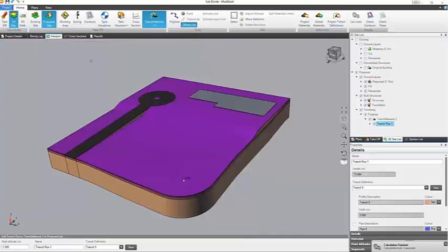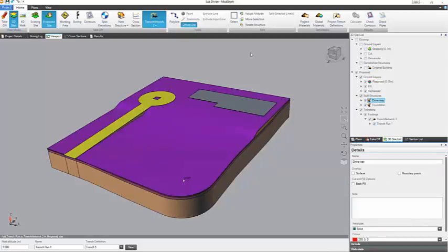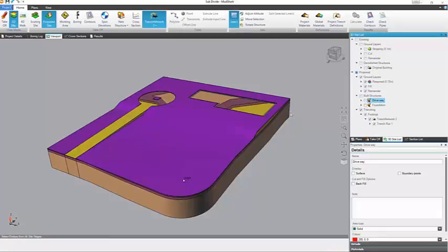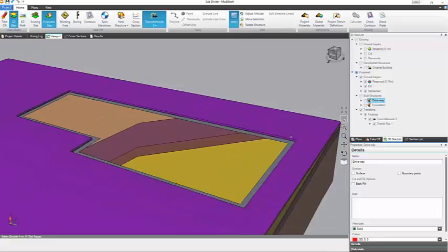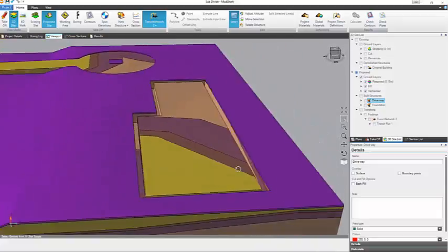And go to 3D, and if I switch off the driveway, remember to go to select to deactivate offset line, switch off the driveway visibility and the foundation visibility, we can see we've got our footing cut out there. In fact, if I switch that off visibility wise, you can see we have our cut out for it.